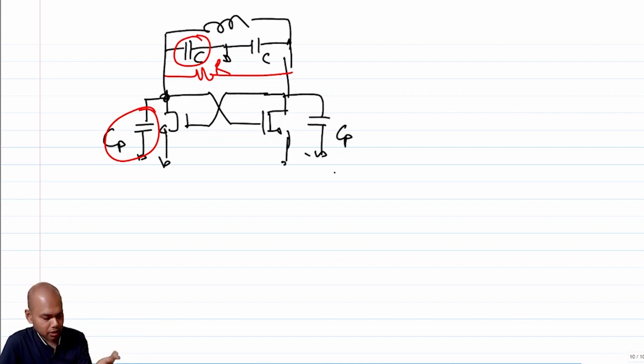That is quite possible because you target a certain frequency, and it is quite probable that the frequency at which the LC oscillator comes out is not the same, because your estimates of this parasitic capacitance are wrong. So in that case, you should have an option of having multiple of these extra capacitances to be switched in and switched out using series and parallel switches, and you can use that to restore the center frequency back. Okay. So now this kind of gives us a framework of designing an LC oscillator with negative resistance.